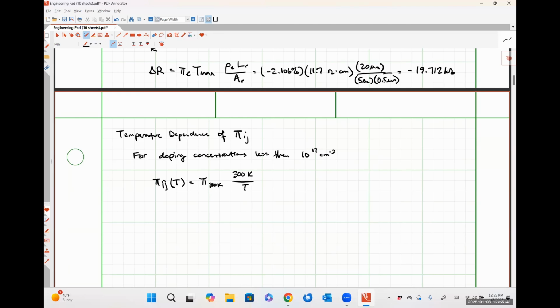Yes. 17. Let me write that better. Yeah. For silicon, whose intrinsic carrier concentration is in the ballpark of 1.0 to 1.5 times 10 to the 10, the doping concentration of 10 to the 12 wouldn't make it particularly conductive.